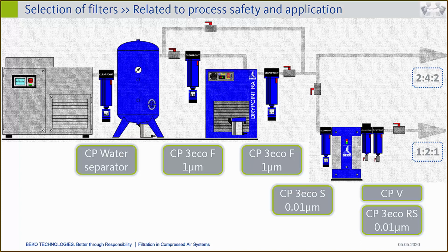But the first priority is always process safety, and to keep the treatment system continuously running in good condition, there's no question about filtration. So we cannot run the risk of reducing the number of filters just to save some pressure drop, because there's still the risk that we have a poor long-term stability of our treatment process.